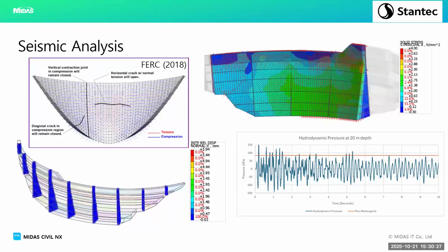The bottom right I've put in there because it's a nice little check. That's an extraction of the hydrodynamic pressures, or the pressures on the interface between the dam and the reservoir, just the time history of the pressures. And you want to check if the model is right, and you want quick little checks. We have tested in-house with my colleague, Ryan, who might be watching,